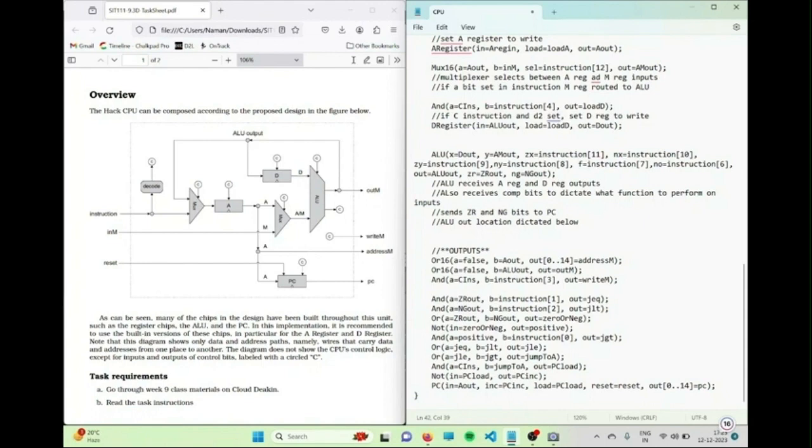For the outputs, we have the out and two control bits, namely ZR and NG, which determine the properties of the result. The code next of two OR gates and one AND gate sets the ALU output in order to successfully write on the data memory.